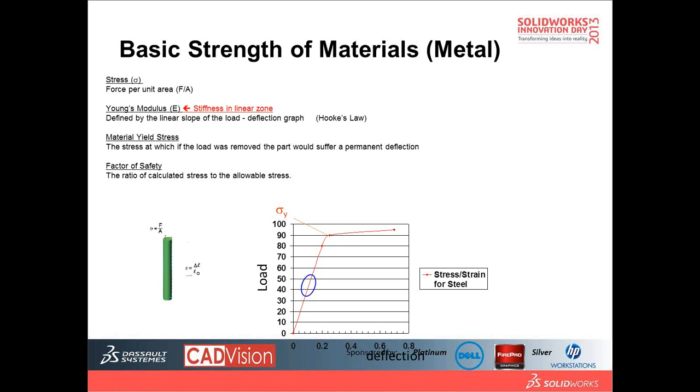The first one is the stress and strain ratio, or should I say Young modulus, is different than in the linear zone. And the second one is that the stress and strain relation could be nonlinear. It's not a straight line anymore. So this is what we have in nonlinear analysis to predict what happens after the yield point.